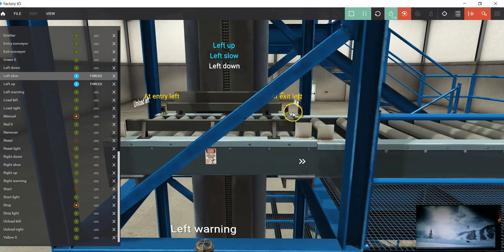So when we're talking about they both have to be high, you have to do that. That's why in the actual program we have that one shot in there that'll give us a trigger pulse that tells us exactly when we're at the right height, and then we can stop it immediately. We can stop it on that scan, and that's really important.